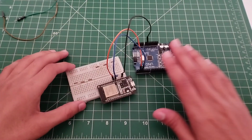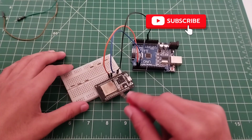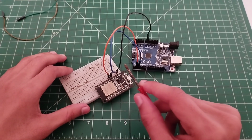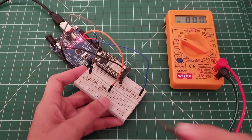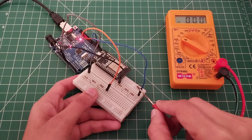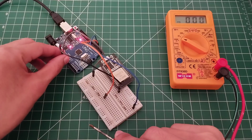Now actually this is not a recommended connection between both the microcontrollers because the digital pins on the Arduino output 5 volt and the maximum voltage that the ESP32 pin can handle is 3.3 volt, right? So for that purpose we will require a set of resistors. Now all of these 6 resistors are creating the voltage divider circuit, and each of these resistors is of 1 kilo ohm. And this blue wire is connected to pin number 3 and this is connected to pin number 2. And this black and gray wire are connected to the ground of the Arduino.